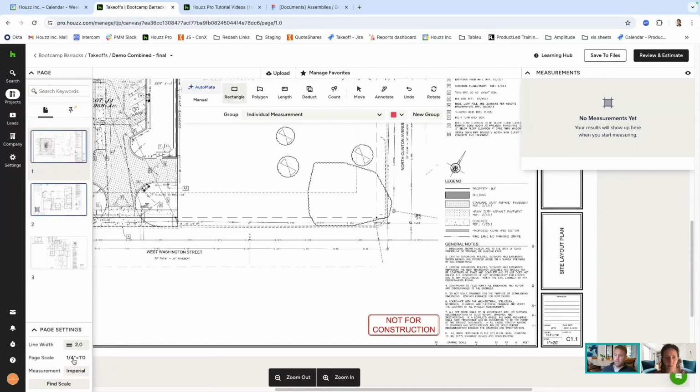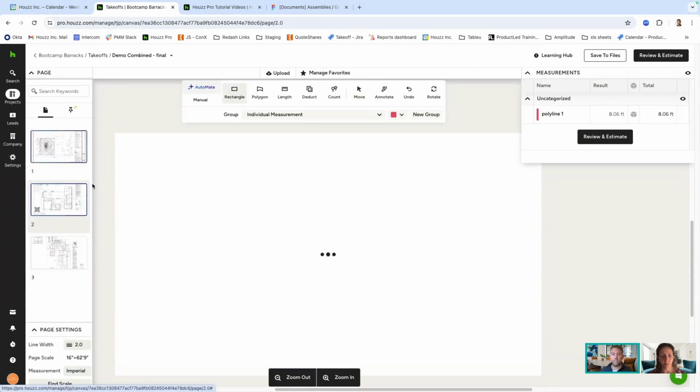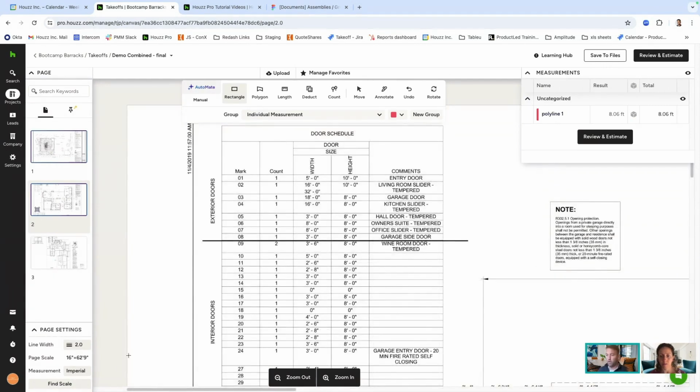So that's just here again in the drop down, and you just come down to 1:20, and that should all be good. So check that out first. As I say, it's usually a mistake you only make once, and it's usually quite noticeable if you do have the wrong scale in. So that's kind of a little bit of the housekeeping.